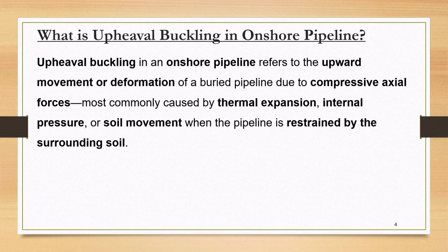What I was explaining is that towards the end you can consider it similar to an anchor, not an exact anchor, because soil has some stiffness. Based on that stiffness we can assume it is basically not a fixed anchor, but it gives a philosophy similar to an anchor.